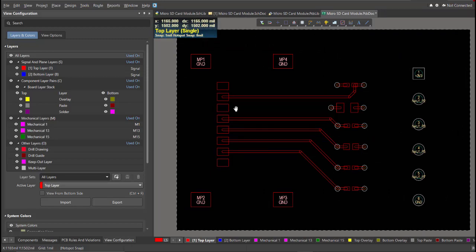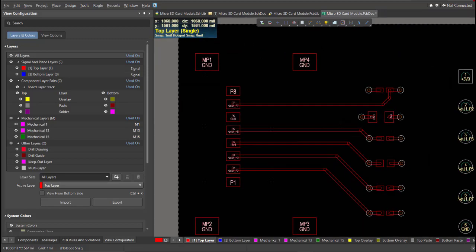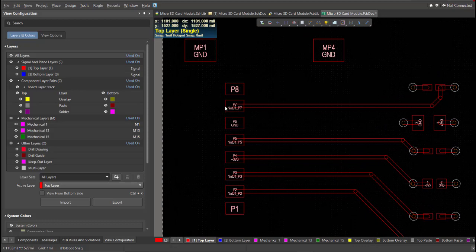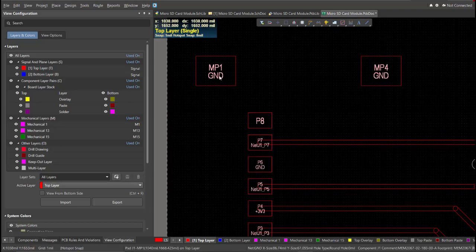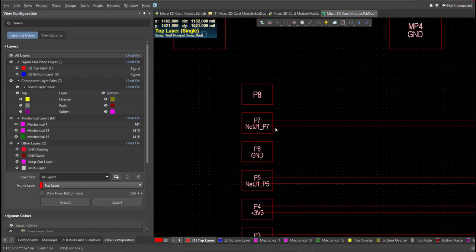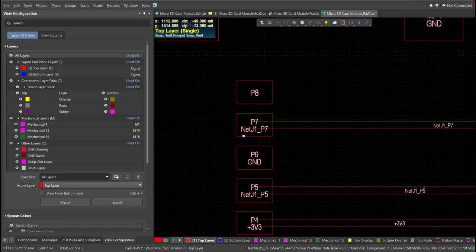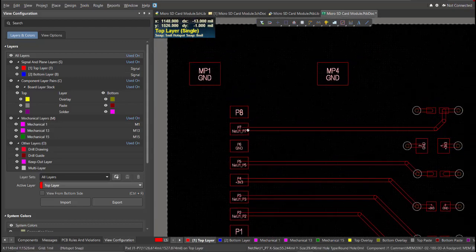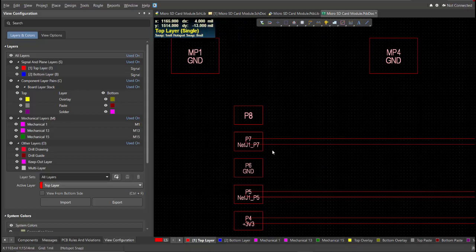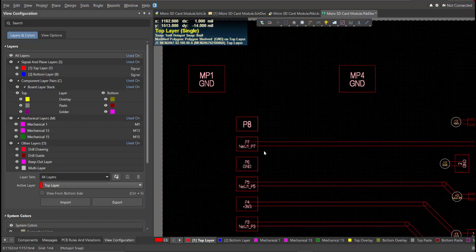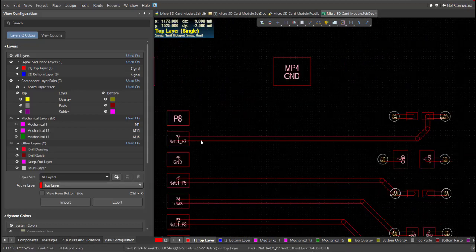Some mistakes in layout are not considering the trace width. The trace width is based on the requirement of the net. For this example, this pad has the ground net and this pin 7 is only a regular pin. If you have a regular connection in your design that doesn't need a thick trace, you can just route it on your PCB.